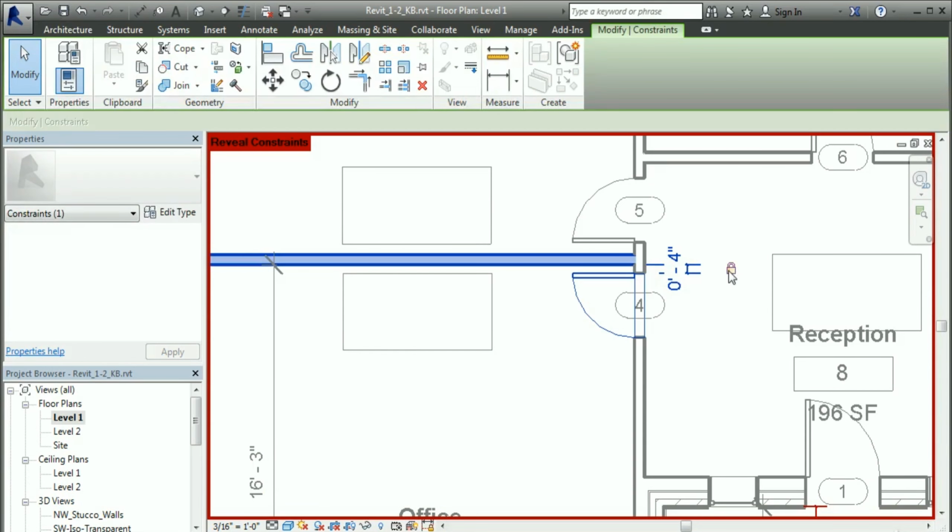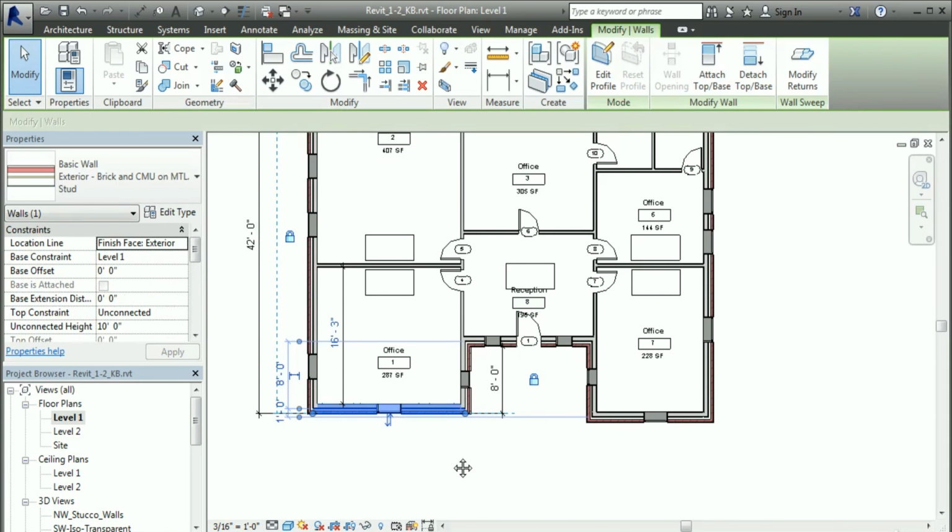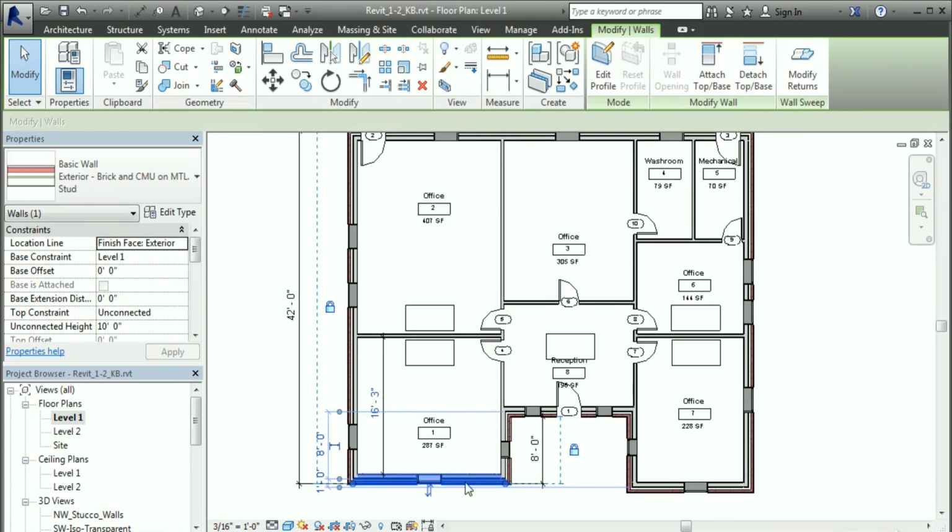So far, our building has been able to shift its exterior walls to reposition or resize the building perimeter without regard to a fixed location. And if you'd like to lock your building down at one point, then you can use a pin to do so. I can go to the Modify panel on my ribbon and choose Pin, and then pick a wall to pin, and then choose Finish Selection, and I can add the pin that way. You can also create a pin by selecting the object that you want to pin down and then picking the pin icon.